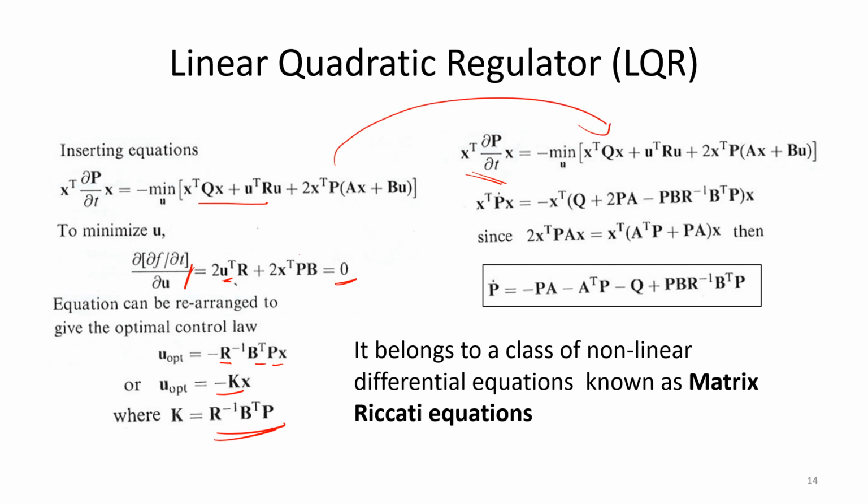So here you have to substitute. So first you take this value from this, x transpose Px equal to this. Okay, so substitute that. So when you substitute this control law, then it becomes like this. So this is my final thing. This equation is called the Riccati equation. But you will understand once you implement this with any simulation software. But here these are the matrices, P you have to concentrate on, and then R, Q.